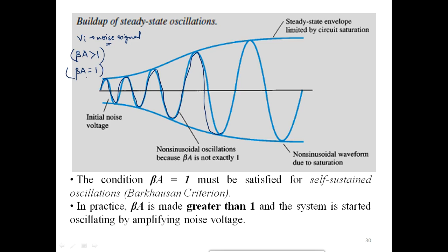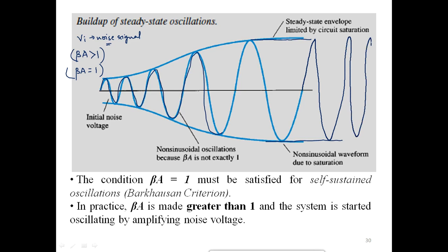When this condition gets satisfied, the amplitude of the oscillations begins to saturate, in the sense they are of the same amplitude. Further, we will be getting signals of constant amplitude and the same frequency. So that was how the oscillations initially build up and then finally attain the steady state.